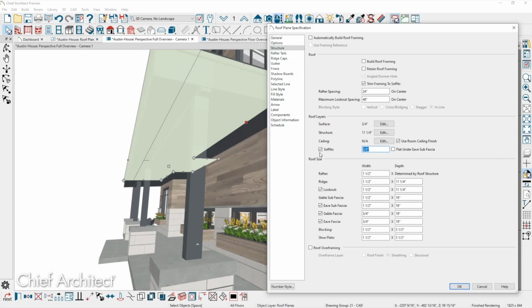The ceiling covering is going to go under the rafter, and then your rafter tail gets smaller for the fascia when you make your bird's mouth, etc. But it ends up showing up wrong. Okay. Have you looked inside of the roof when you build it, or the individual roof plane, which I've selected here?